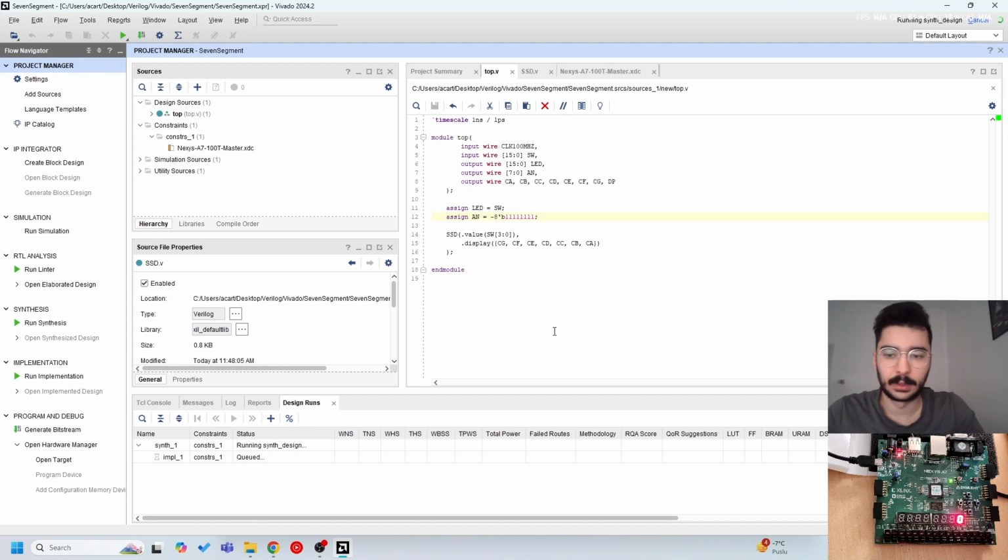Let's wait. And the thing that we need to somehow exploit is the fact that we can turn on and off each digit and display different things on each digit, but not just at the same time. One power of FPGA is we can do it really fast, and we can take advantage of the human eye, because our eyes cannot process the visuals that fast.